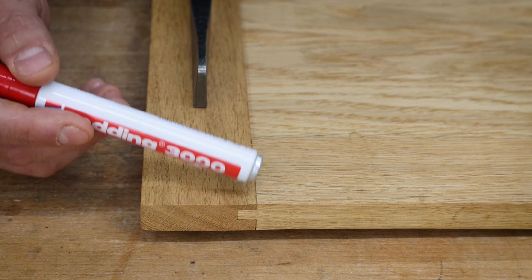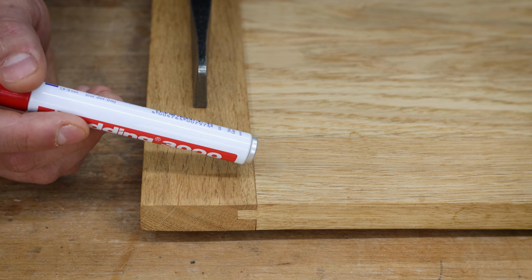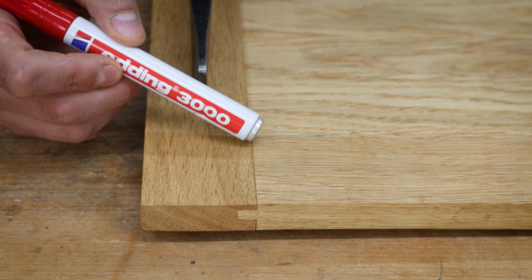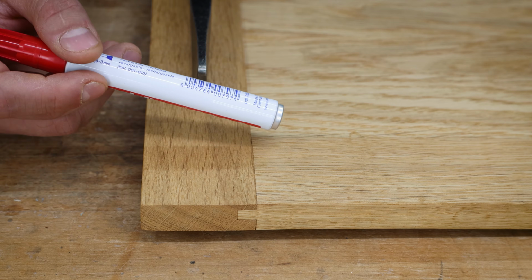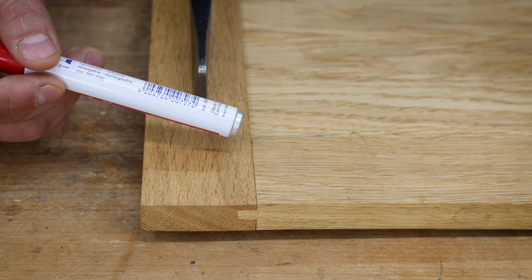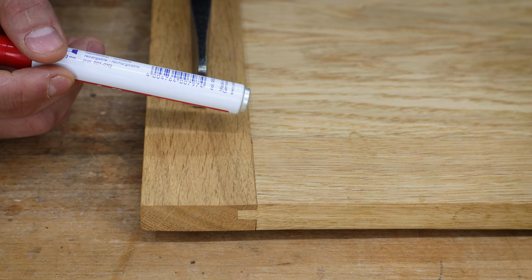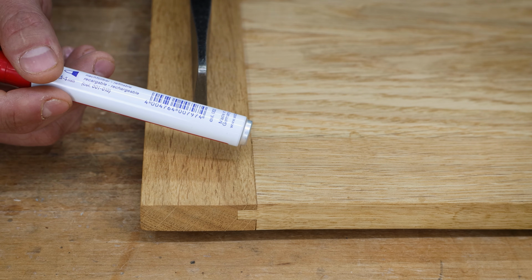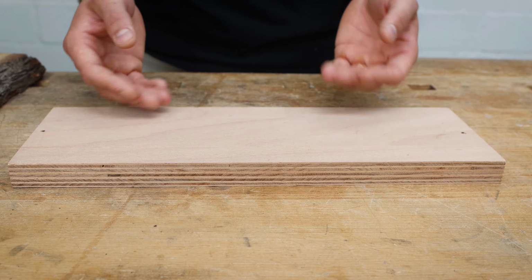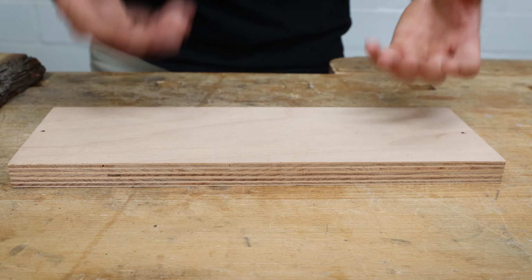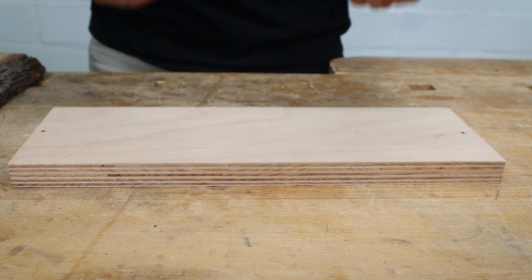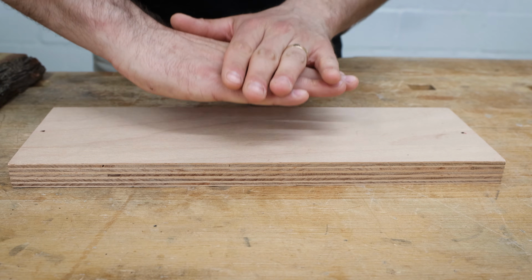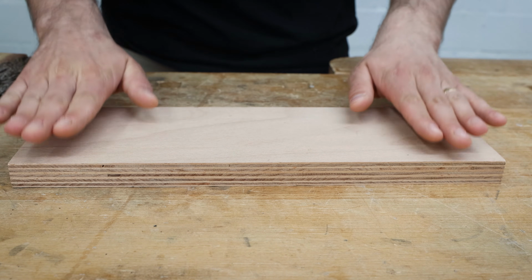Why are they not? Because, remember, wood movement is a percentage game. And the width of the board here is so small that also the wood movement is pretty small. As a rule of thumb, you can get away with this kind of joint up to a width of about 12 centimeters. If it's wider than that, you might get into trouble. Plywood can be way wider than 12 centimeters. You can get it up to 2.5 meters or even wider, and still it's holding together, although there are cross-grain joints or cross-grain lamination going on.